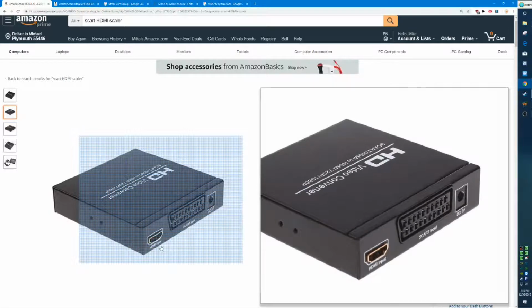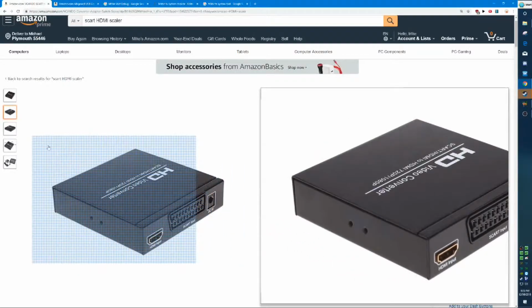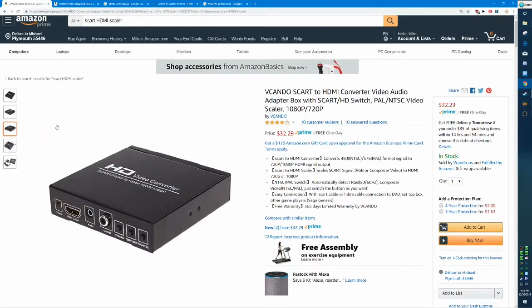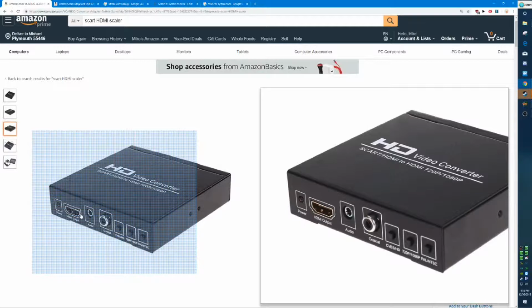In addition, it also gives us an HDMI input that supports everything down to 240p, computer resolutions like 800 by 600, all the way up to 1080p 30. And on the output side here, we're given an HDMI output which has no HDCP encryption, which is really useful. One of my primary uses for this device is being able to remove HDCP encryption and extract audio at the same time for older projectors, or bringing a Blu-ray player into a video switcher that doesn't support HDCP, that kind of scenario.